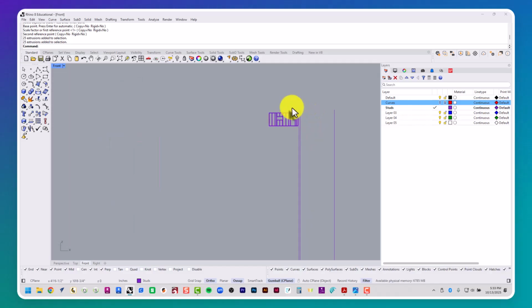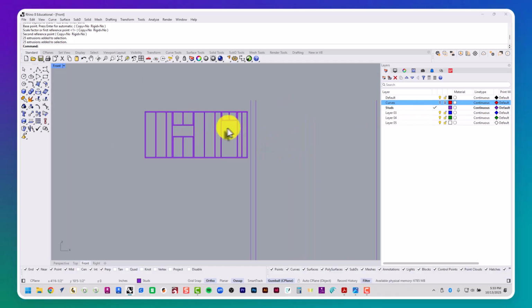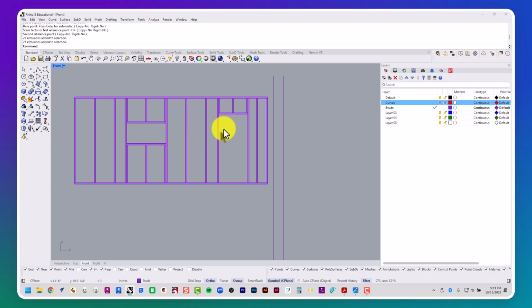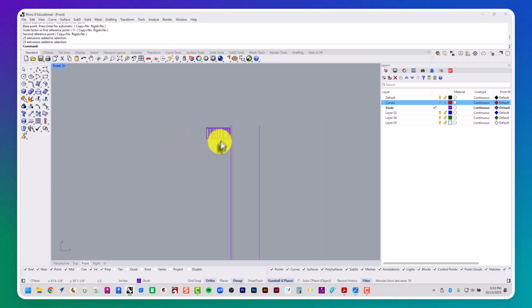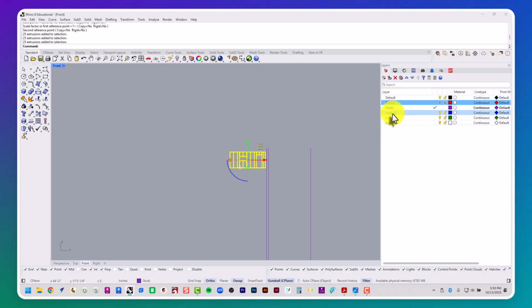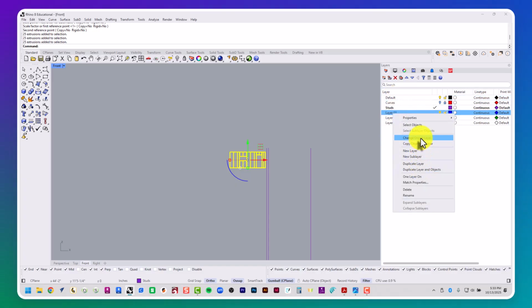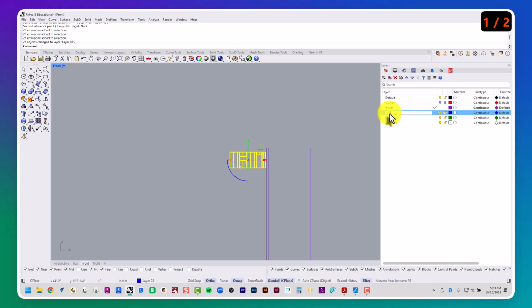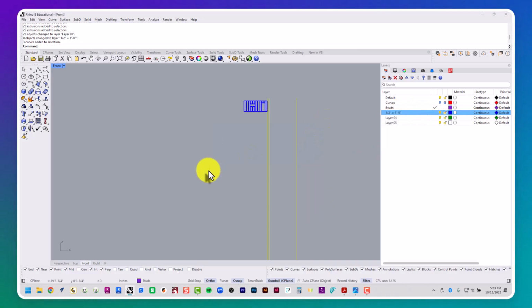Okay. At this scale, this is completely ready for 3D fabrication. I can laser cut this, 3D print this, make it by hand. I'm not sure about CNCing it, but this little guy is our 3D print. So I'm going to select this object, right click on layer 3, change object layer, and change the name of this layer to 1/2 inch equal to 1 foot 0 inches. Change object layer. I can get rid of these 3 lines. I don't need them anymore.